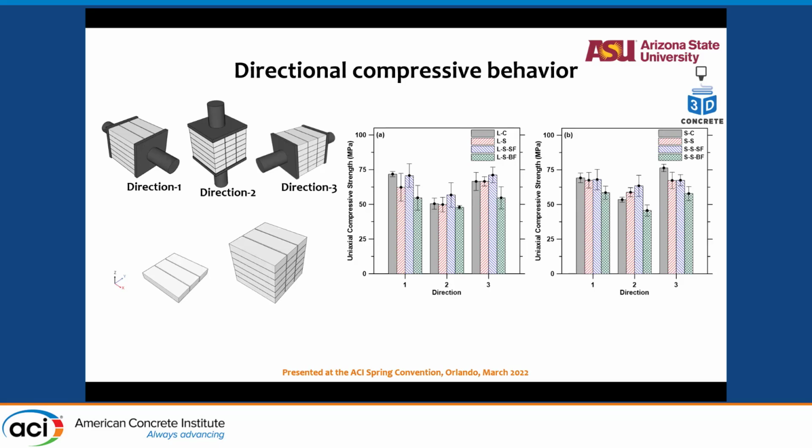The failure is along shear in that direction. You're not capturing flexure at all. You cannot use your conventional flexural equations. Again, you see that mistake being made in a lot of publications where people flip it and do it and report a certain strength. Really, you're not testing flexure because there is not compression and tension alone, there is shear as well. So for that specific reason, we're not measuring, and we don't recommend measuring directional flexure.